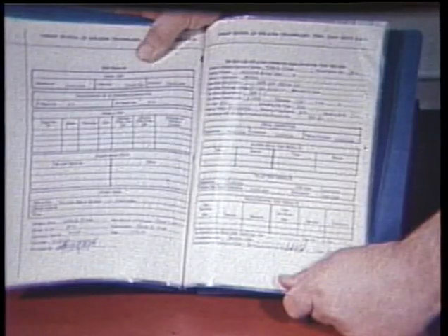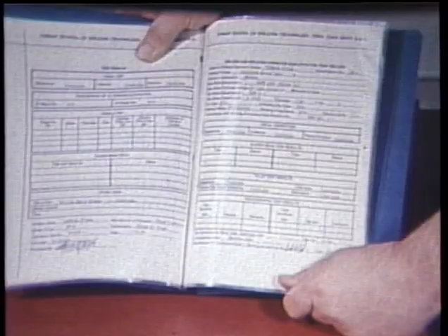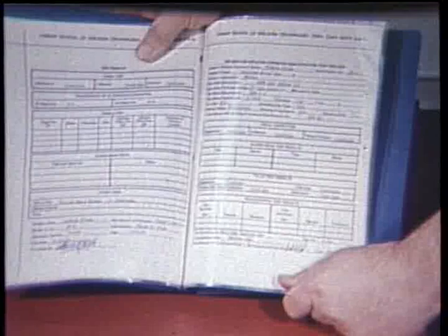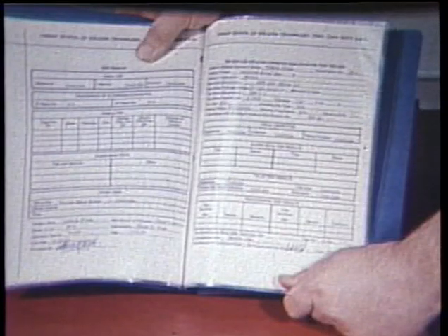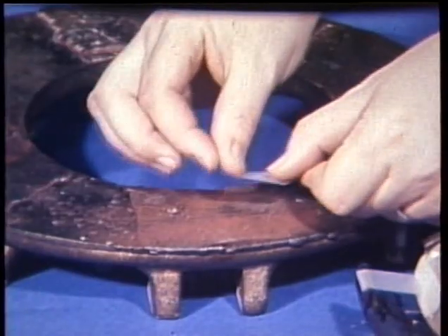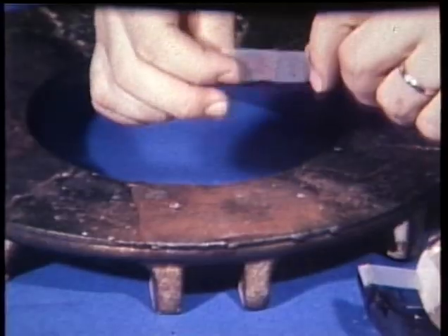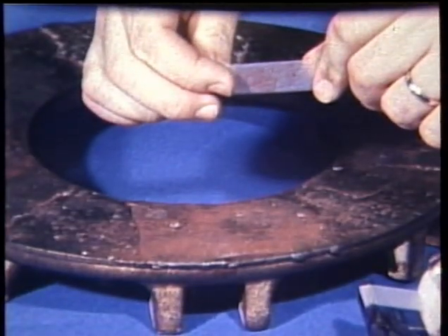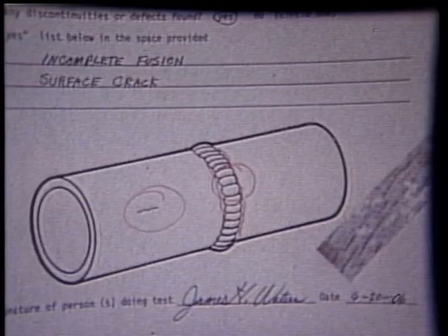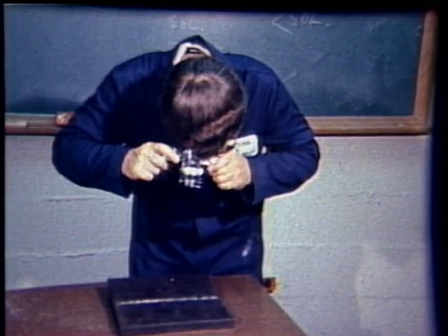Once all inspections are complete, concise records of the test results should be developed. A permanent record can be easily made by one of two ways. Clear, transparent tape can be placed over the indication to transfer the particle patterns to the tape. The tape can then be placed over a simple sketch of the weldment on the test report form, or a photograph can be taken of the test surface and attached to the final report.